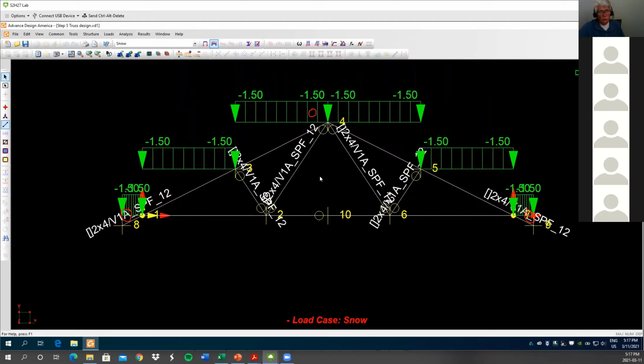to your bottom chord. You understand? Of course, it says the snow load on your slides because I screenshot. It says 2.5. Oh, okay, that's when you add that. Because it says snow load 2.5 kPa. Yeah, but that's kPa. What's your tributary width for each truss? 0.6. Okay, so you're right, it's kilonewtons per meter, not kilonewtons per meter squared. Okay. So there you go. You're on your way.